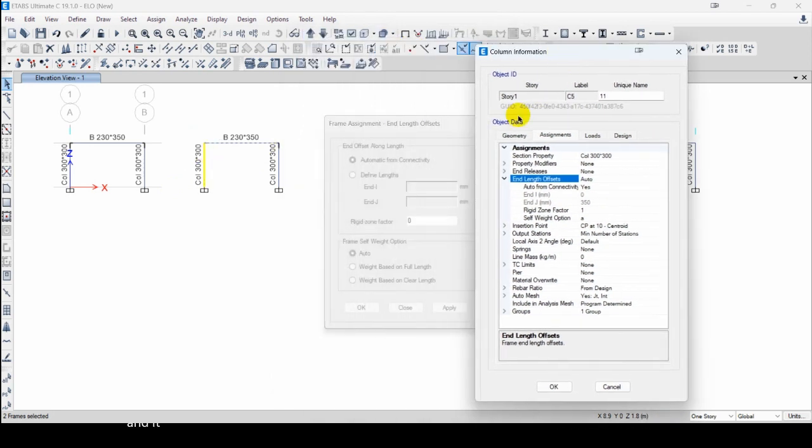If we see the bending moment and shear force diagram for this structure, we will get something like this for the beams, 150 mm from the center of the columns, and for the columns it is like this, 350 mm below the beams, from the soffit level of the beams to the base.